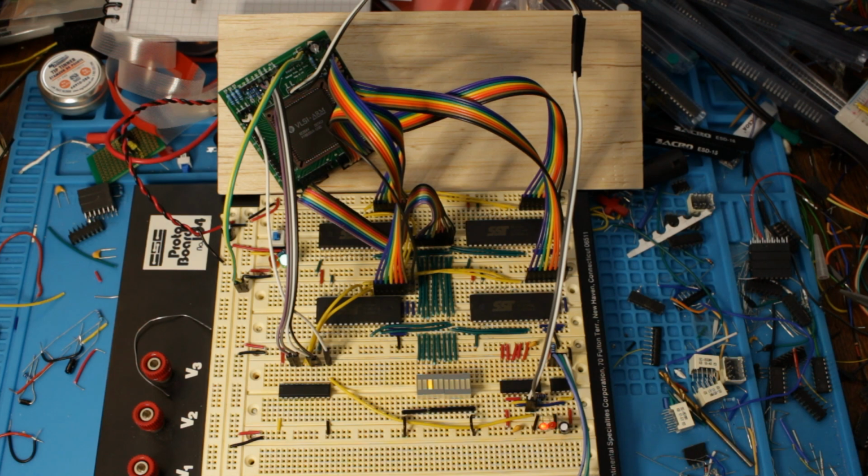And that'll be going to 4 bytes before where it read the first branch opcode from. So we should see it count on the counter here, ignoring the bottom 2 bits. We should see it count up like 0, 1, 2, and then, well, that'll go down and wrap. Let's take a larger number, but suppose it said 10. We'd expect it to say 10, then 11, then 12, and then go back and say 9, then 10, then 11, and then go back and say 8, then 9, then 10, and so on. So we can kind of see what's going on here. I wonder if I can slow it down a bit more. It does look like it's working.